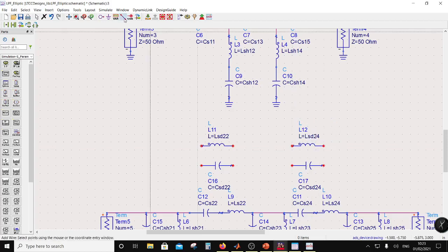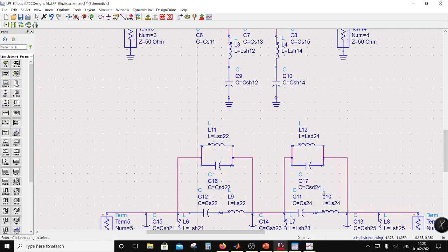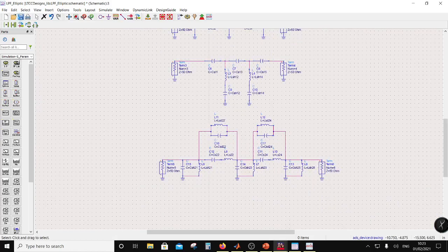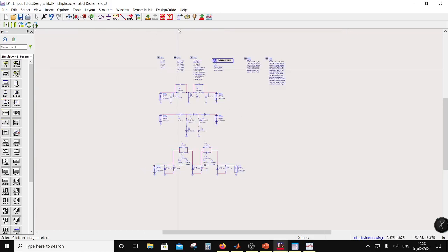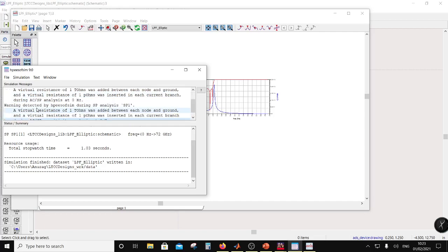Okay, so I'm all set with the elliptic bandpass filter after this transformation, and this component will come in shunt with this series resonance circuit. And you will not find this in the books because the books stop at Chebyshev, right? Even Pozar would stop at Chebyshev. Okay, so this is my elliptic bandpass filter. So I'm ready for simulations. Oh, there is a problem, is it?